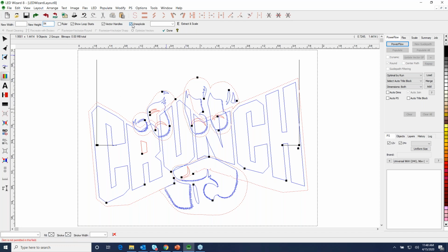84 inches. And I'm unclicking on explode. So one way you can tell if something perhaps has exploded data is that the loop direction would be black, which represents an open loop. And further, you'd have all these what we call start endpoints or loop starts, and that's what these black boxes are. So I'll show you the next file that'll have a whole bunch of these on an object. So I don't need to do that in this case.